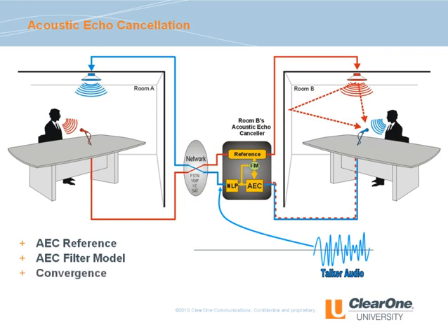The next component in the acoustic echo cancellation process is the NLP, or nonlinear processor. The NLP is best described as an intelligent suppressor that recognizes and removes any remaining residual echoes that may occur after echo cancellation. Proper calibration of the audio conferencing system is critical to NLP performance and maintaining full duplex by preventing unwanted suppression of the local talker's audio.